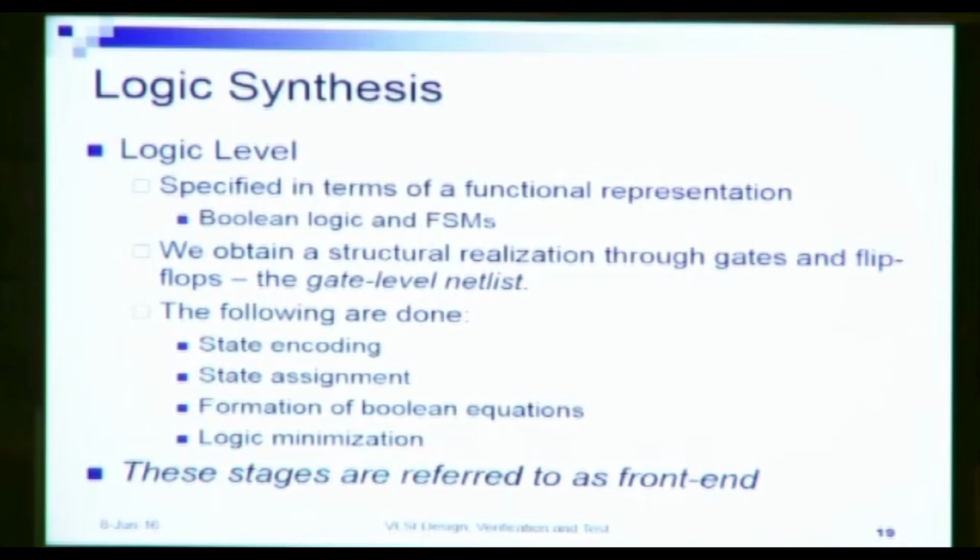This RTL description, as well as this FSM, has to be encoded in terms of Boolean equations, and for the FSM we also have to do a state encoding, assignment, and realize it in terms of a digital circuit.